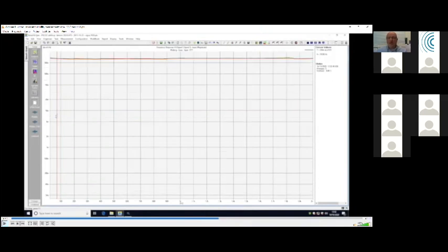And you can see we get a straight line, which is actually 1 over the mass. The mass, if you've noticed, was 3.85 kilograms. And the 1 over the mass should be the accelerance, which is this value up here, which I can't read, which is something like 2.259 meters per second squared per Newton.